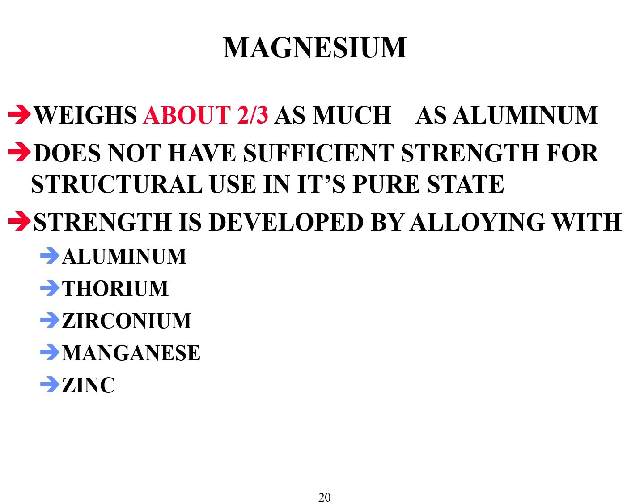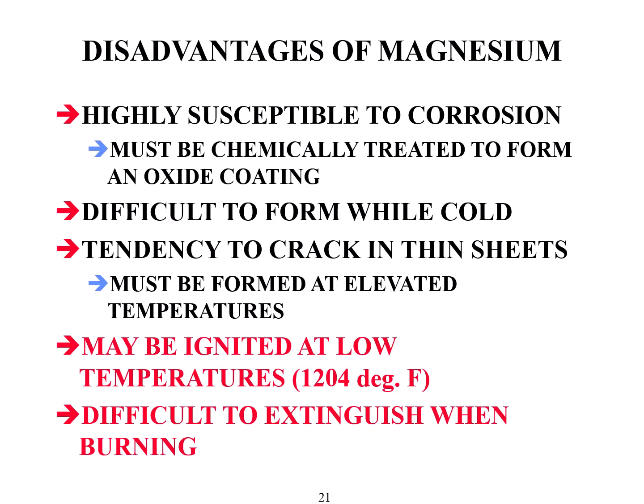Magnesium alloys are used all over aircraft, including engine parts, turbine engines, piston engines, where you need lightweight but very high rigidity, very high strength to hold shape. Magnesium alloys are a little more difficult to protect from corrosion, but they do have that property that's very, very desirable in aviation. Therefore, you see a lot of it. Magnesium is kind of a magic metal when you blend it with aluminum.